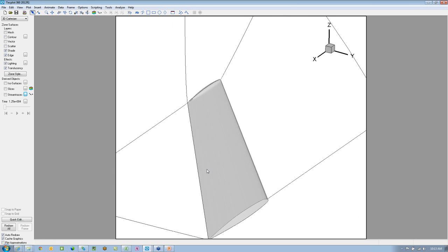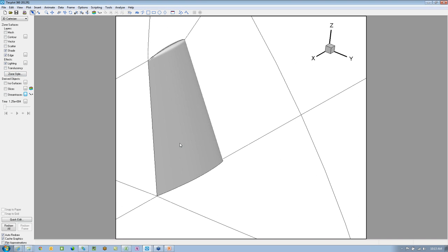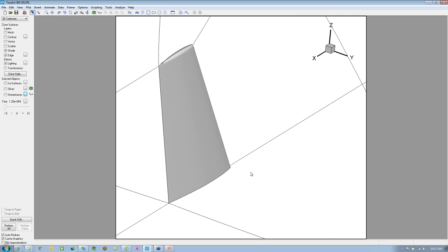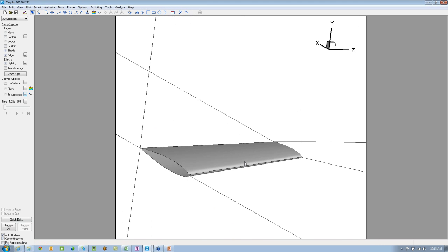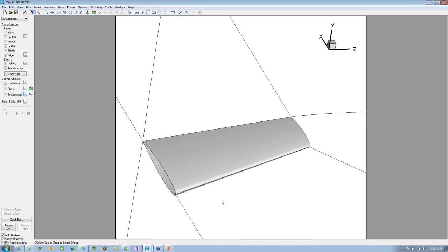A couple of things that I get a lot of questions on when I'm out talking to customers is around the axis of orientation. The rotation axis is typically at the center of the overall flow domain. If you want to change it, you just put the mouse where you need it and hit O. Doing so will reset that orientation axis and allows you to more quickly evaluate the system. Now you can rotate around a given point. And I do understand that the audience view is going to update a little slower, so you may not see me doing that in real time.